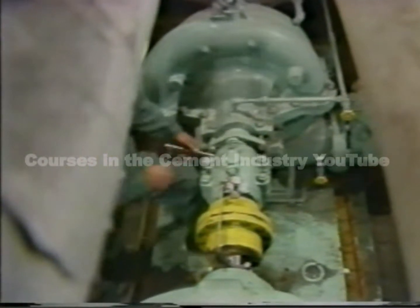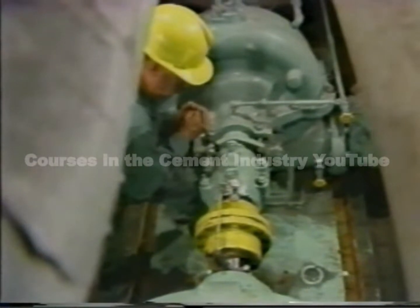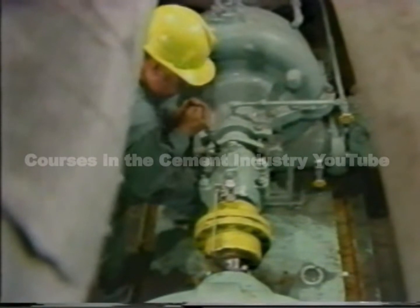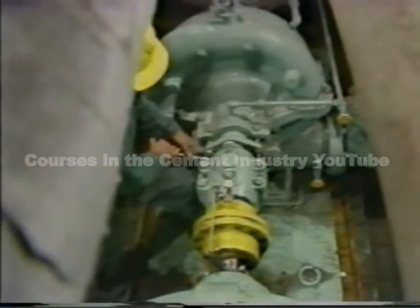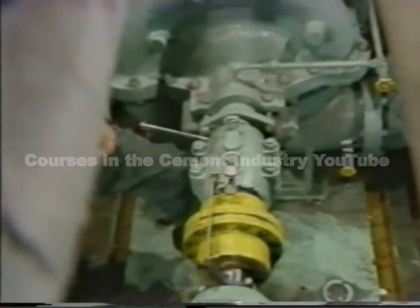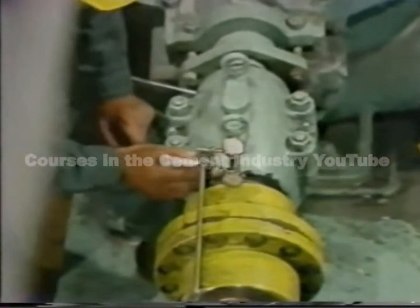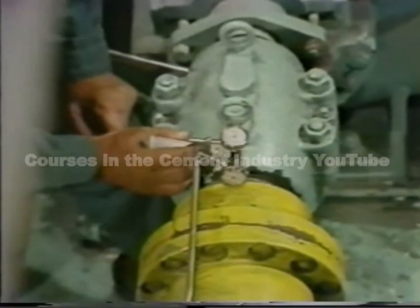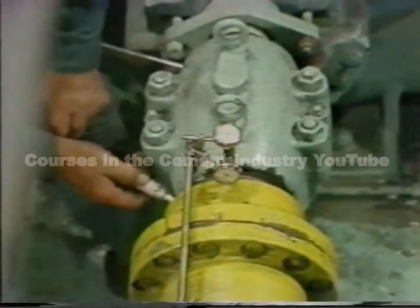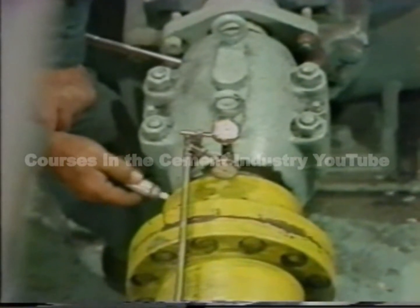Once the dials are mounted, the next step is to rotate the shaft to get the dials on top. Since we'll be taking readings around the shaft, it's a good idea to mark the shaft at 4 points. The bearing housing is usually a handy spot. The marks should be about 90 degrees apart. This is where all the data will be gathered, at each of these marks.